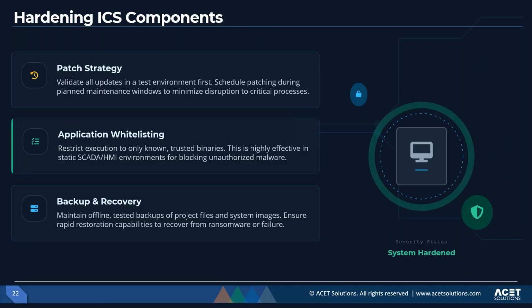These backups need to include control logic, firmware versions, configuration files, system images, and database snapshots. Regular recovery testing is equally important. Backup data is only useful if an organization can restore it quickly and correctly during an incident. In the event of ransomware, hardware failure, or unauthorized configuration change, reliable backups allow the plant to restore automation systems and resume operations with minimal downtime.